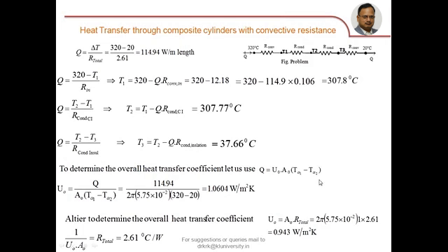Very simple. So a tedious problem can be simplified and reduced into a simple one, provided you are given the value of U_o, the overall heat transfer coefficient. As an engineer, it is our responsibility to give the value of U_o to avoid such tedious calculations in power plants or process industries.